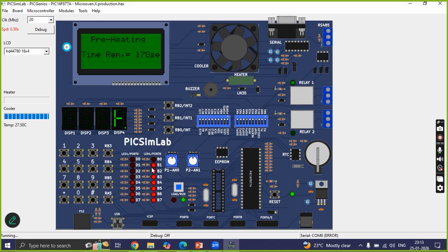After setting the temperature, the system goes into preheating mode. This means the oven is getting ready and heating up. We programmed a specific 180 seconds countdown that simulates the oven reaching the desired temperature. During this phase, the user cannot set the cooking time. The system effectively blocks the next step until the preheating is completed. This demonstrates how we manage sequential dependency in an embedded system.